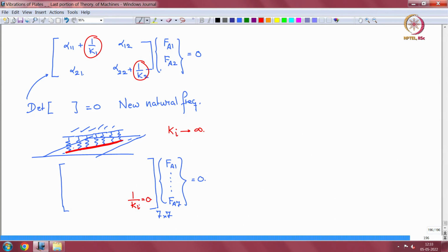Then this will approximate a zero displacement constraint along that line. In actuality, there will be some minor displacements happening between, but it will effectively be a line constraint. The more springs you put, the better you get. So you get a line constraint along that direction.